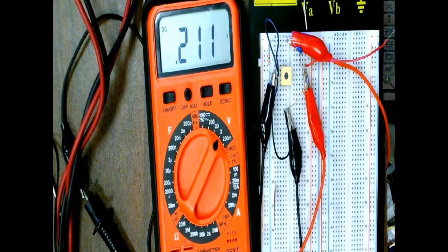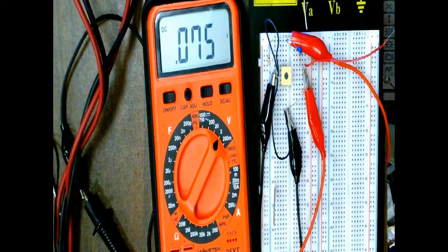By the way, there are some solid state temperature sensors, an LM34 and an LM35. I think the LM34, one of them's centigrade and one of them's Fahrenheit, but these are integrated circuits. So they primarily use a thermistor inside, but they compensate for the non-linearity of the thermistor. These guys are very, very accurate. I've got one. It looks like a transistor. It's got 3 leads on it, and I think we've got the data sheets. I'll make sure we put those in there.